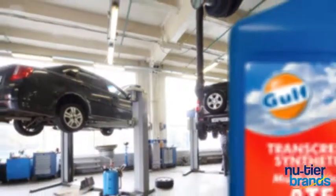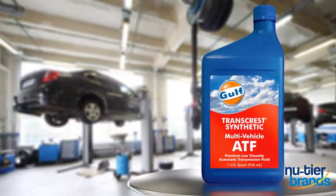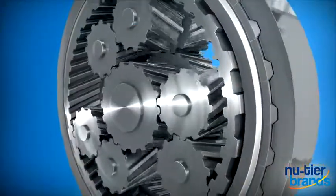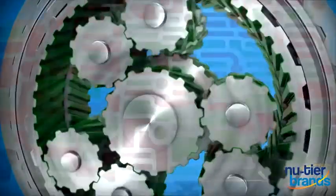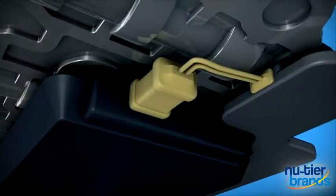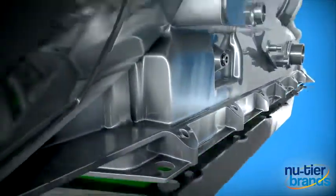The one component of the entire system that's critical to all these parts working together is the automatic transmission fluid, or ATF. Every ATF is a precise blend of different chemicals because it has to do a lot of different jobs. It acts as a hydraulic fluid to engage clutch packs and shift the gears. It acts as a corrosion inhibitor and wear protection for the planetary gear sets. It has to flow easily from -40 degrees Celsius to over 200, even in fine valve assemblies. And it's got to have low conductivity and be compatible with all electronic components.